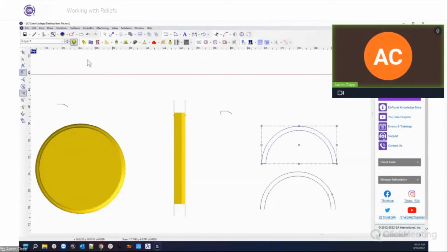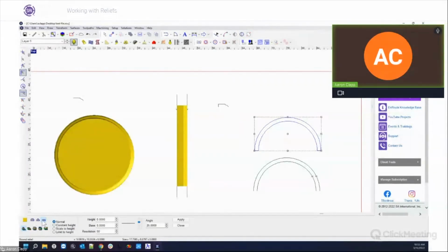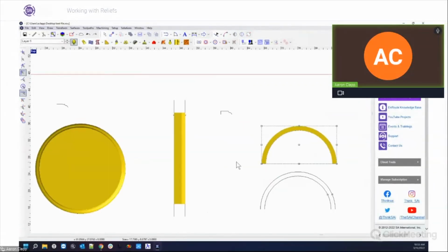And so then all I have to do is add a relief, just like we did before, and then line up my sweep sections, which I can do easily by using the snap tools, and then do the same process all over again, and it would do the same thing on a crown molding type situation, or an arc, or whatever kind of shape.